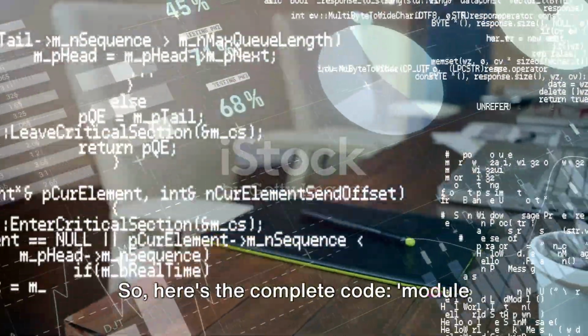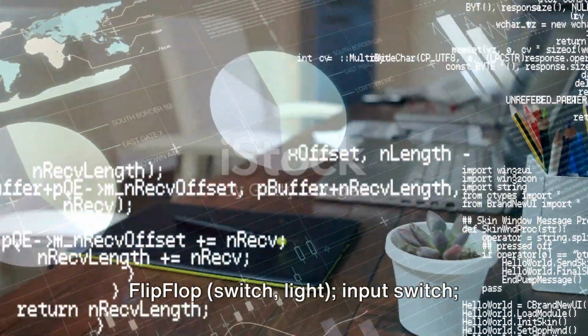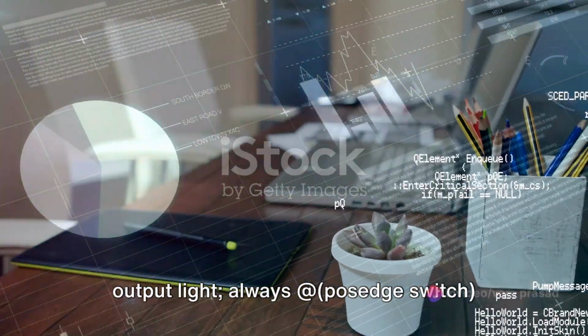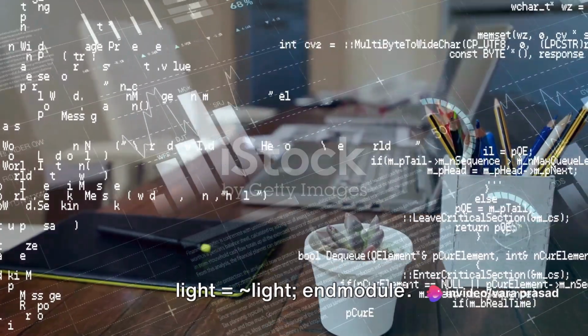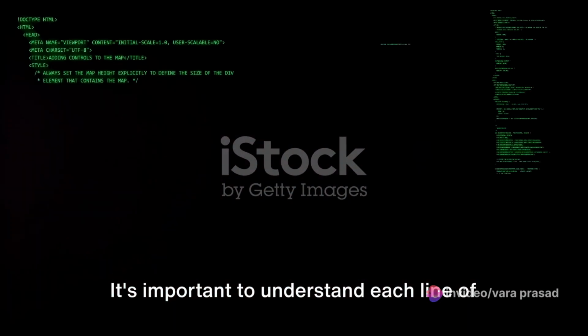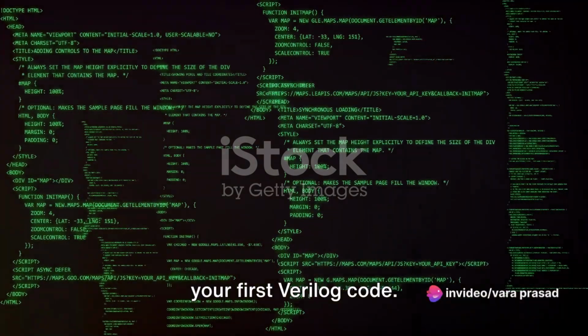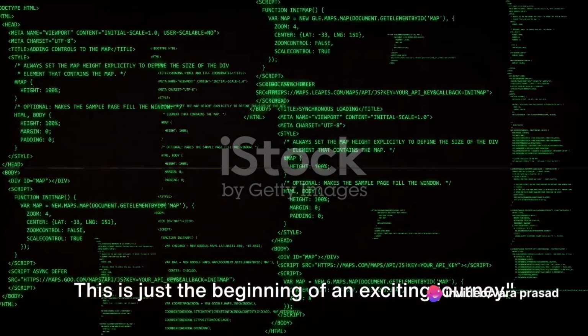So here's the complete code. Module flip-flop, switch, light, input switch, output light, always posedge switch, light equals sign tilde light, endmodule. It's important to understand each line of this code as it forms the foundation for more complex digital systems. Congratulations, you've just written your first Verilog code. This is just the beginning of an exciting journey.